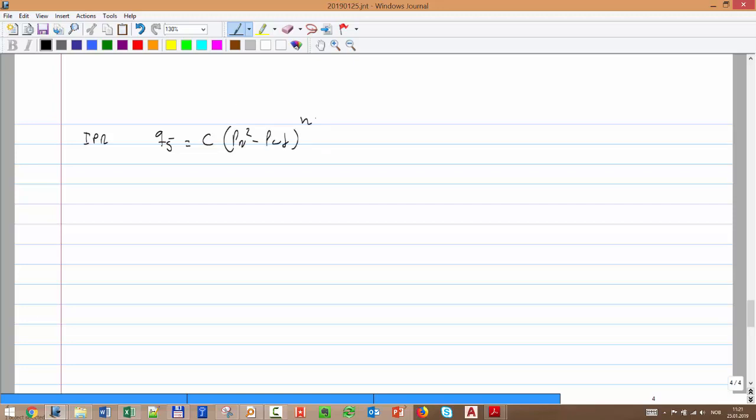So let's create here a table where we say the unknowns and the number of equations we have. Here we have simply one equation, and how many unknowns? Reservoir pressure usually comes from material balance, from how much I have extracted, so this is typically an input.